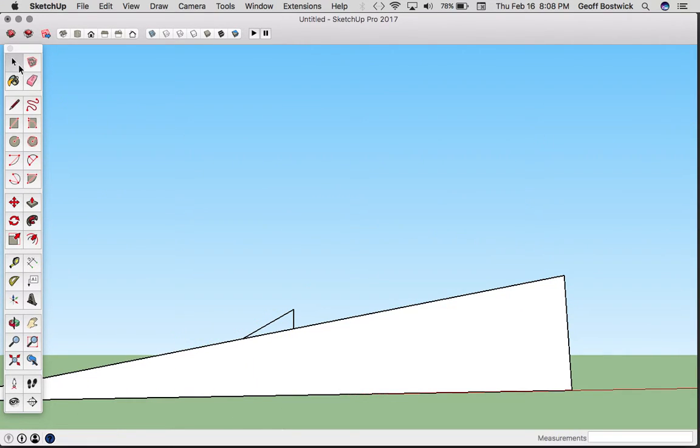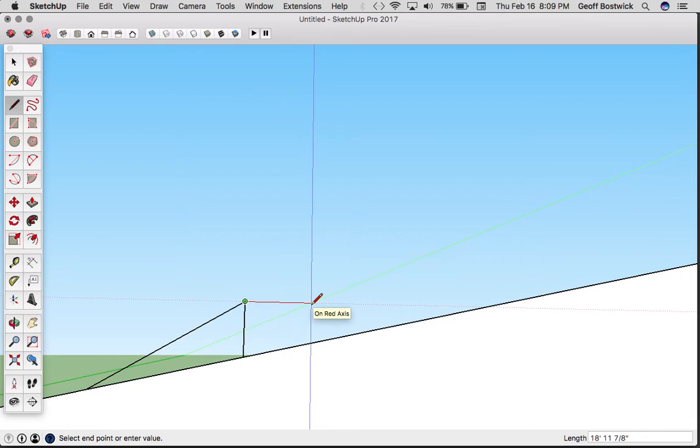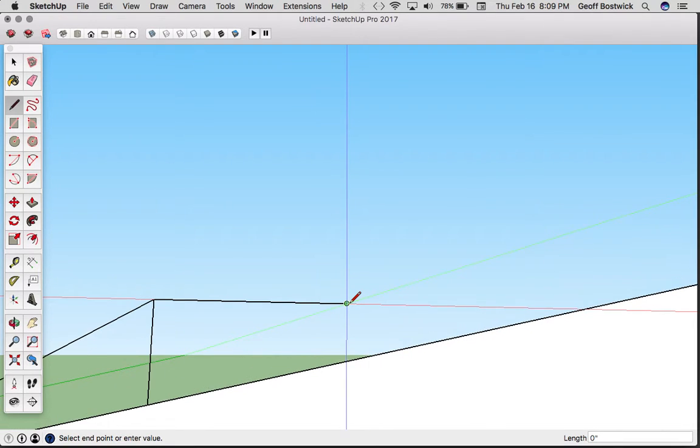And I can go back to my line tool. So I've hit the space bar, which is a shortcut for the select tool, and then I go back to the line tool, and I can determine how far we want the table to be. So the gap is going to be, I don't know, 30 feet. Not 30 inches, I just typed 30 and pressed enter. What I want is 30 feet with the apostrophe. There we go. So then let's make it be about 5 feet tall.